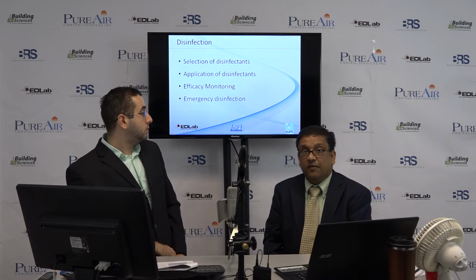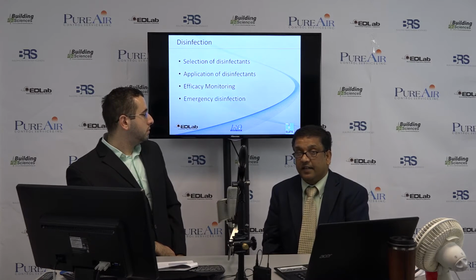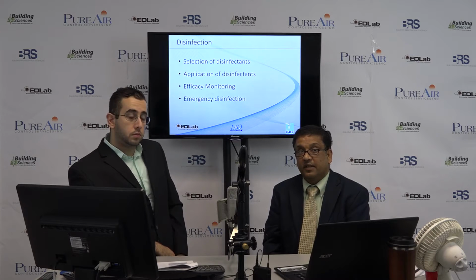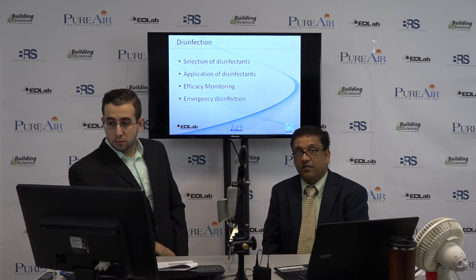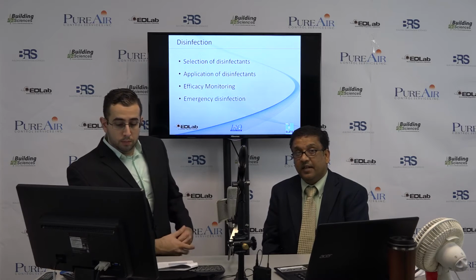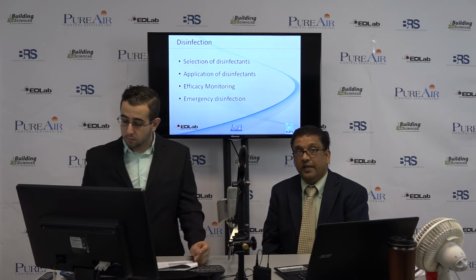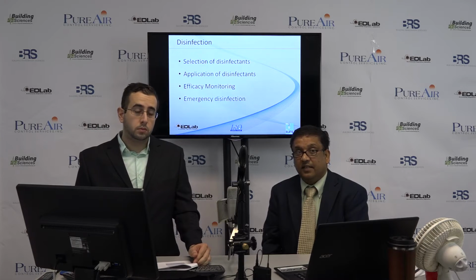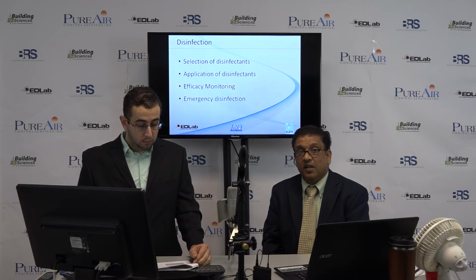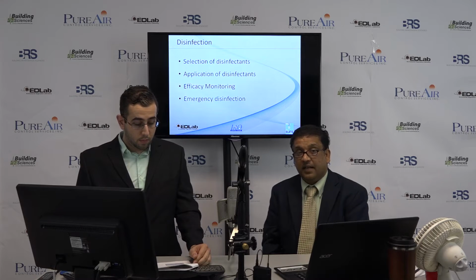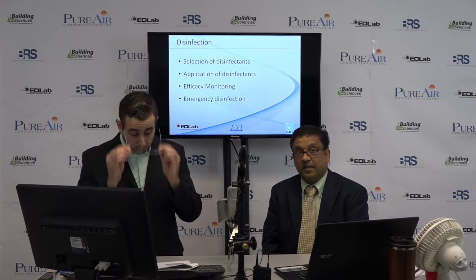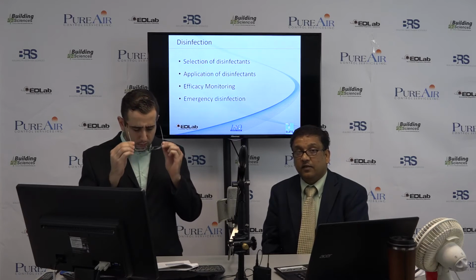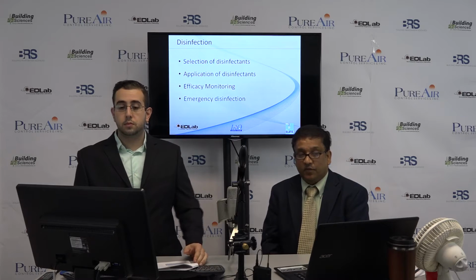Sometimes a situation comes when you have to do an emergency disinfection. Again, it should be performed as per the guideline made by the manufacturer of that disinfecting technique, either chemical or physical, but it should be put in place immediately when an emergency arises. When I say emergency, I mean when you have a proven case, a proven source of bacteria, and for sure that particular hotel or tower or whatever is contaminated with this bacteria, then the disinfection should be taken immediately and addressed in that way.